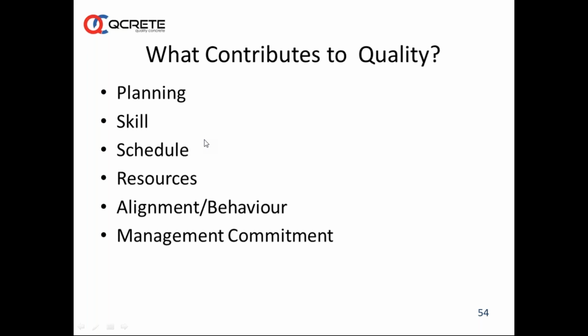Also, another point we need to understand is we cannot go on adding this admixture several times. Normally, 2 times is recommended. Once you have boosted this slump by using a chemical admixture on site, you can do it another time. You cannot go on doing it and disturbing the concrete. Generally, we have this concrete time of 2 hours given by IS 4926. What it means is, once the water comes in touch with cement, you need to use this concrete in 2 hours, unless you are using a superplasticizer cum retarder, or you are using the concrete in cold temperatures. This is given by IS 4926.